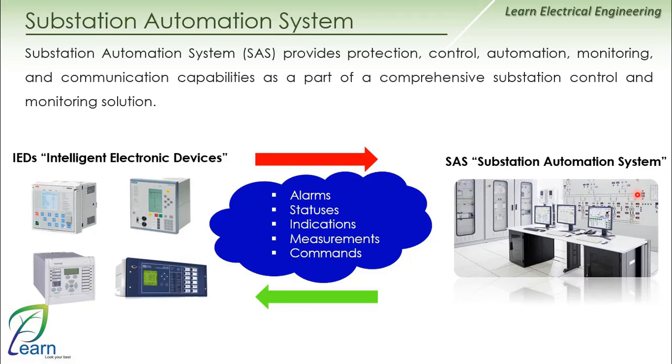Now, was it just a single line diagram? Of course not. Each of these components had an indication lamp next to it, allowing you to know whether the component is closed or open. You also had something called the annunciator, and its purpose was your alarm system, where you could start seeing a set of alarms related to the GIS.